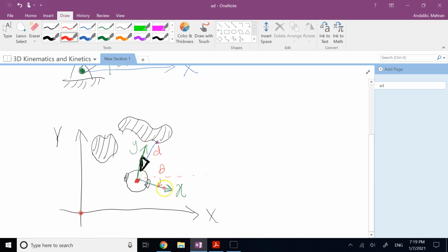So you see here, I need a secondary frame with respect to which my sensor is measuring some stuff, and then I would add the current position of the robot to the position of the point with respect to the robot to find the position of the point with respect to a fixed world coordinate, okay? And then I can add more points and then create a map of the environment.